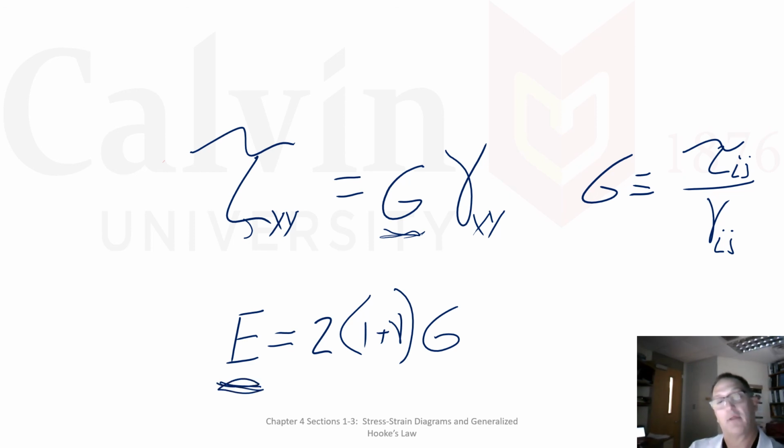Typically we're going to measure Young's modulus off the stress strain chart. We may measure Poisson's ratio, or we may simply use the 0.3 or 0.29 to get to where we need to be, and then we calculate G, that shear modulus. We can test for shear modulus. That is a material property test we can execute, but we don't always do that.